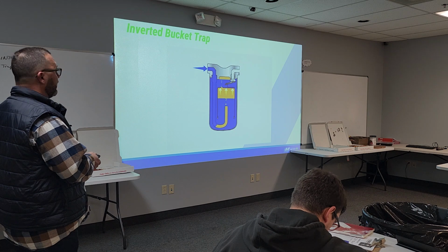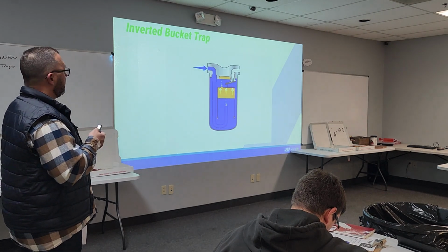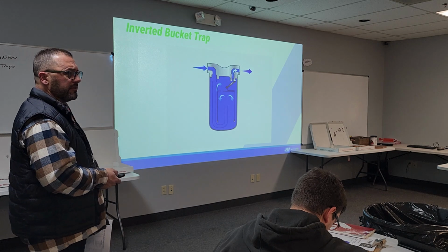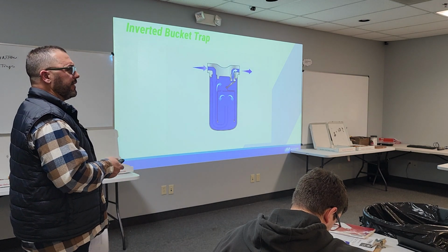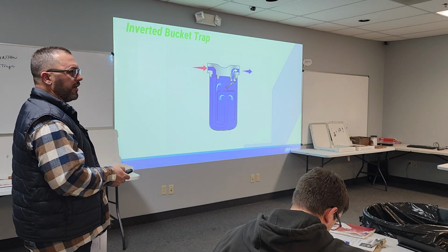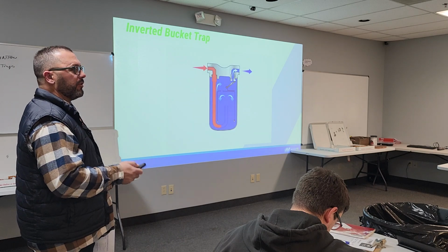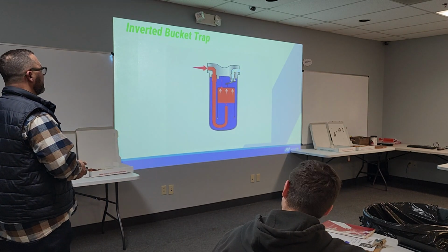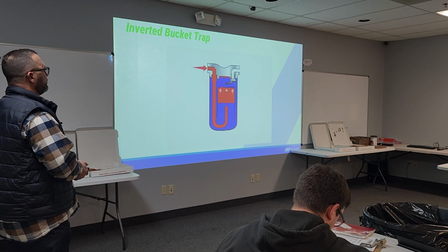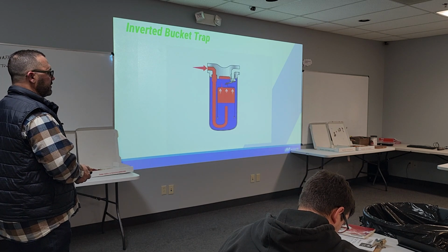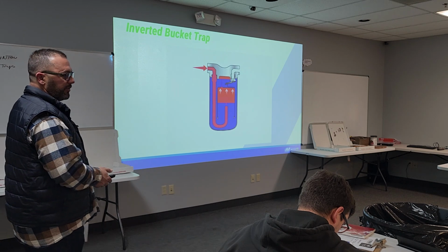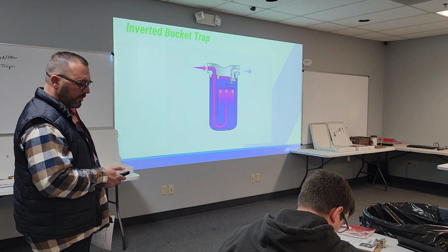Again, just like an F&T, you've got to size them for the pressure class. So it's not like a valve where it's a 300-pound valve or a 600-pound valve. It's more about the orifice. And if you try to use a 15-pound rated trap in a 150 psi application, it's going to lock shut. It's not going to work.